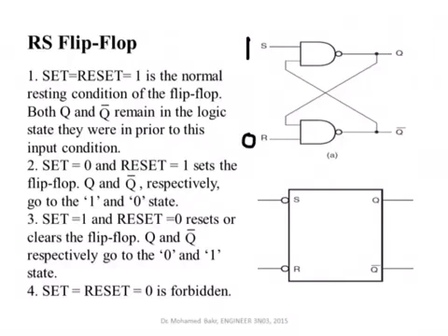And remember, when I put 0, 0 means it's active. So indeed, I want to reset this flip-flop. I would like to make Q equal to 0. Now, because this is 0, the output from the NAND will be equal to 1, regardless of anything else. Okay? And because Q bar now is 1, and you have S equal to 1, the output from the NAND will be equal to 0. So indeed, the RS flip-flop has been reset.